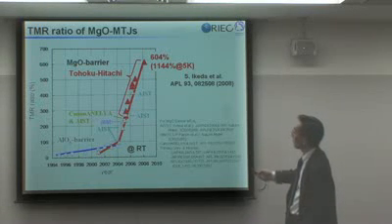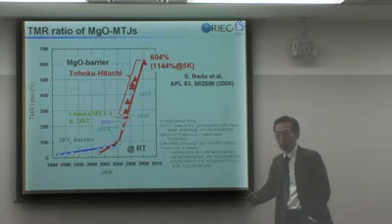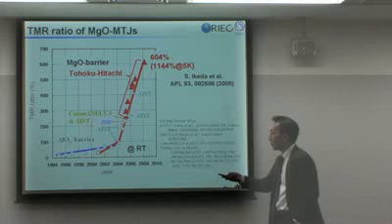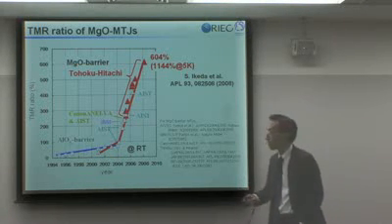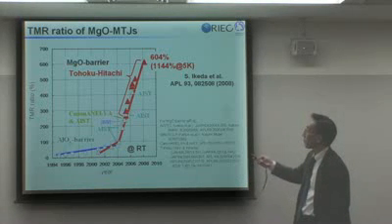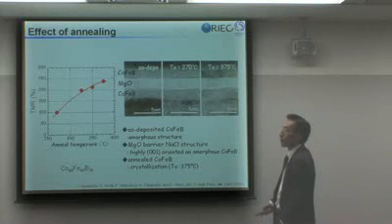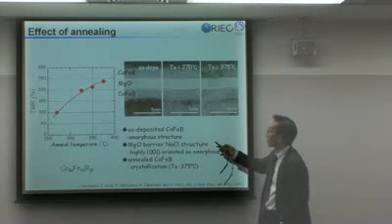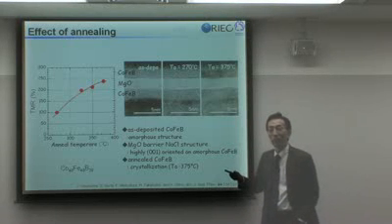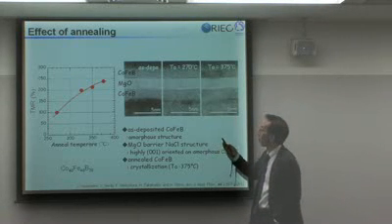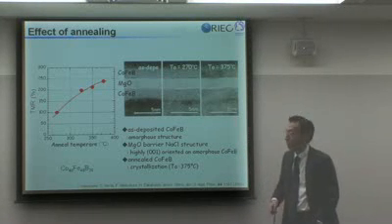So the reading part has been overcome. It used to be that TMR was not high enough for integrated circuit applications, but now it has been overcome by introducing the magnesium oxide structure. It's nice to point out that you do not have to have a crystalline structure and epitaxy to achieve this required crystalline structure for this high TMR ratio.